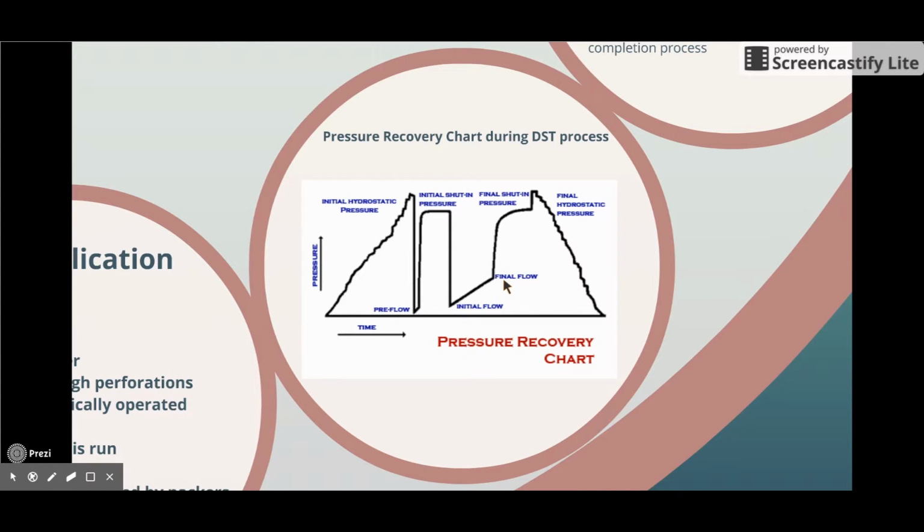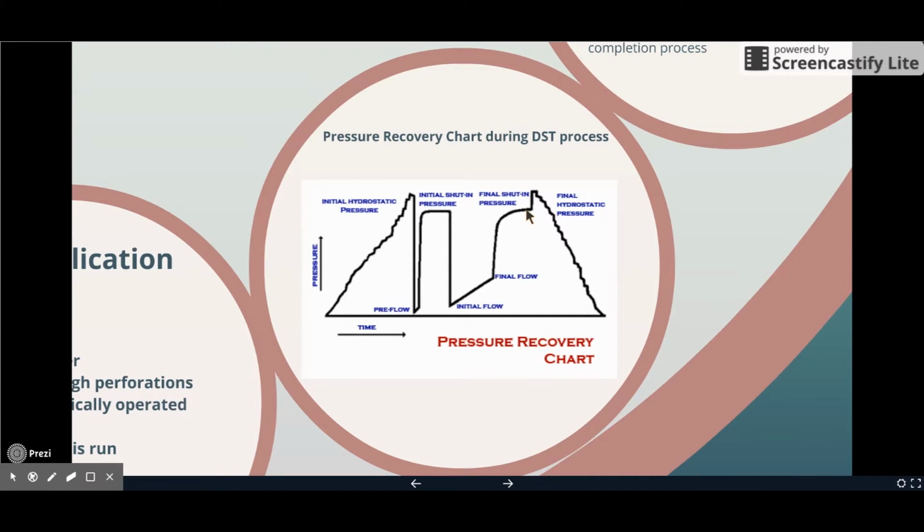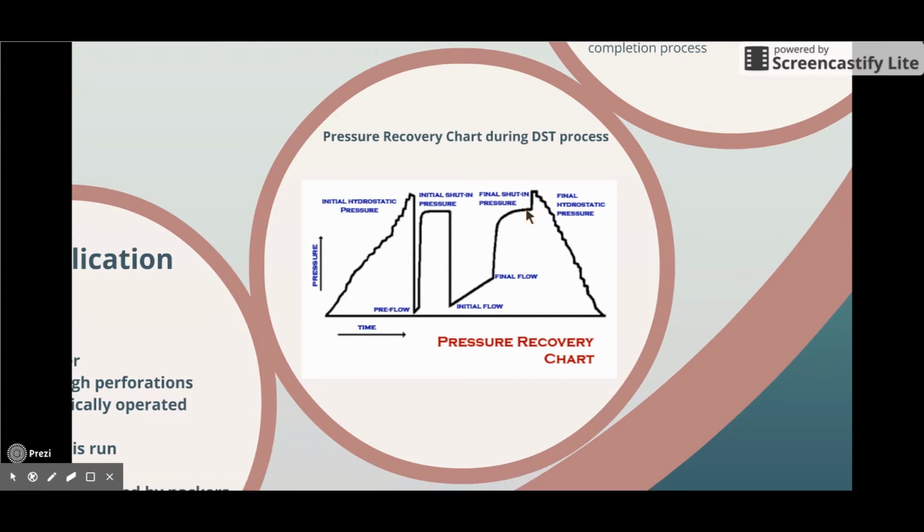The shut-in valve is closed. The second build-up period is started. The second shut-in period. The pressure increases as the fluid below the shut-in valve is compressed due to the pressure build-up. The end of the second shut-in period and end of test.